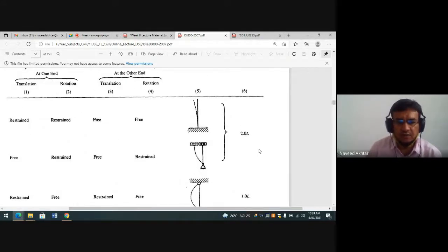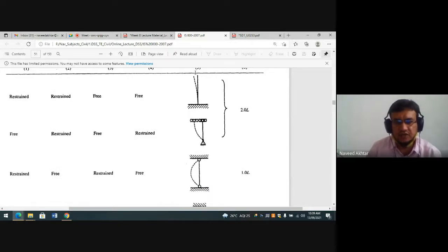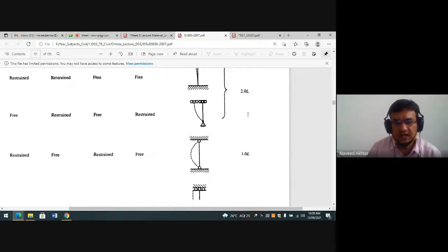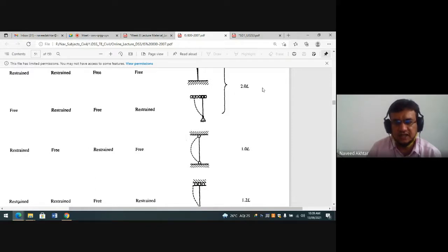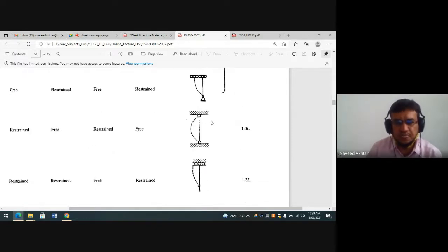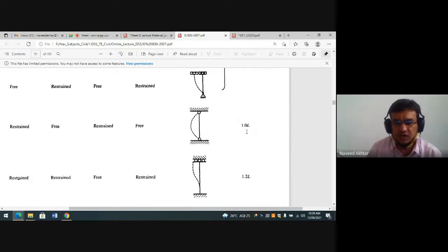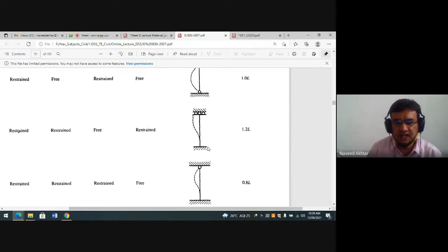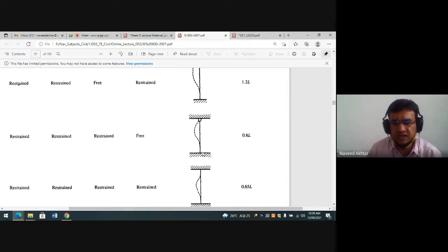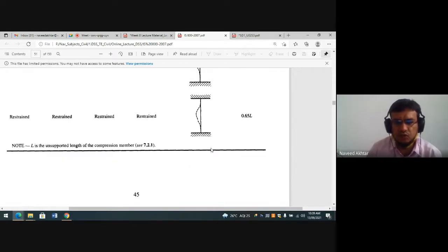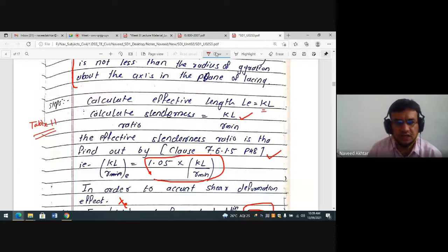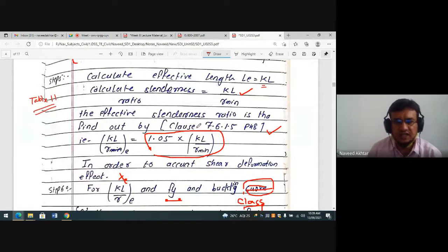कॉलम के लिए इफेक्टिव लेंथ, अगर एक एंड फ्री है दूसरा फिक्स है 2L, एक एंड हिंज है दूसरा रोलर सपोर्ट है, then also 2L. Value of K is 2. Both side hinge condition है, K value is 1. One side fixed, one side roller, K value is 1.2. One side hinge, one side fixed, K value is 0.8. If both ends are fixed, then K value is 0.65. So likewise, we have to find out the effective length.